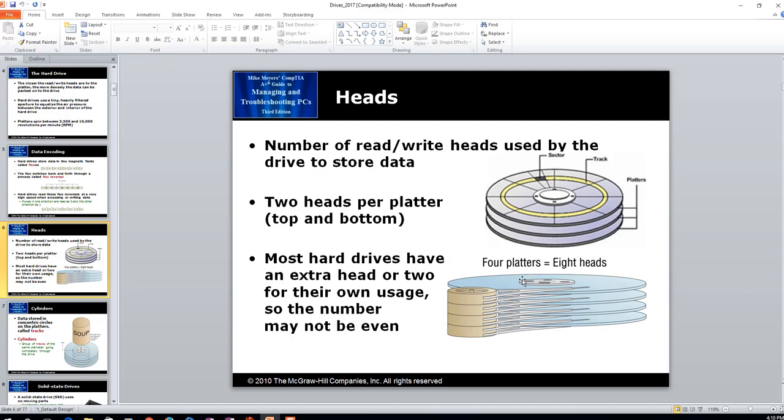That's why today's hard drives, especially in laptops anyway, have an accelerometer designed to sense when there's a sudden g-force, and they will actually park or shift the head very quickly over to an area on the platter that is sort of sacrificial, can be damaged. Sometimes you hear this called parking the heads. Parking the heads means putting the heads over to one side. I actually don't know whether it's on the outside or the inside, but to a place where if the head hits the platter, it's in a space where there's no data stored.